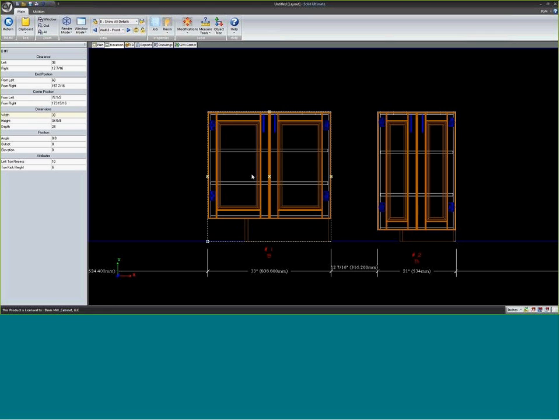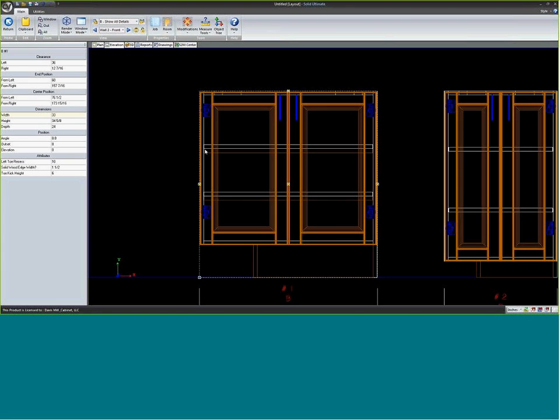Again, nothing happens. If I click this cabinet, remember over here I have 2 sidebar attributes currently, but I dropped a new wildcard on there. If I hit enter twice, a new sidebar attribute shows up. And also see here a little drop down, the little shelf got bigger. If I change this to 3 inches, you see that shelf get bigger.